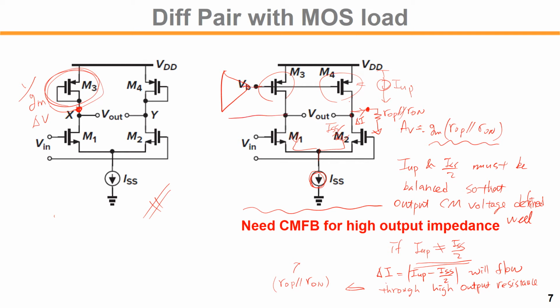So we need the help of negative feedback to find the proper bias level VB by monitoring those two output levels. We put very high impedance resistors at both outputs and take out the middle to find the output common mode voltage.